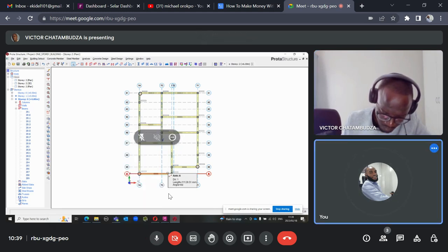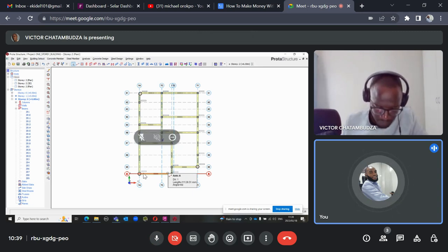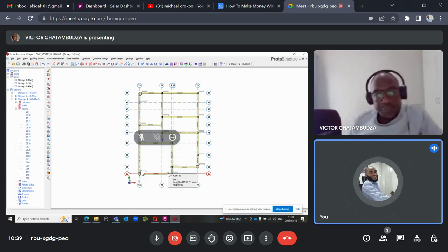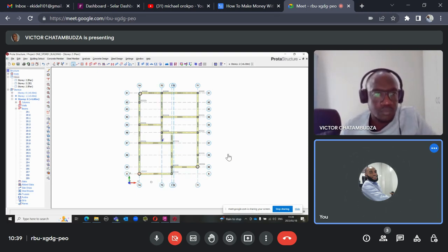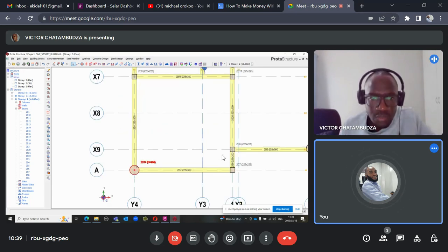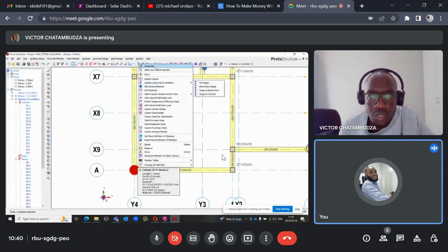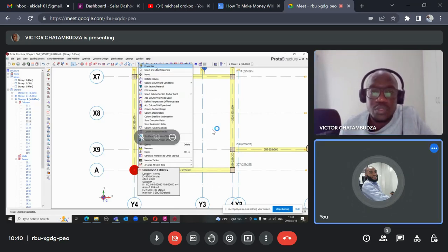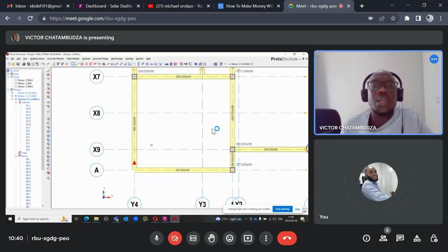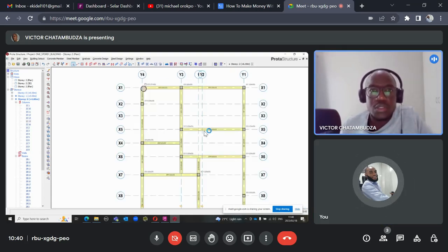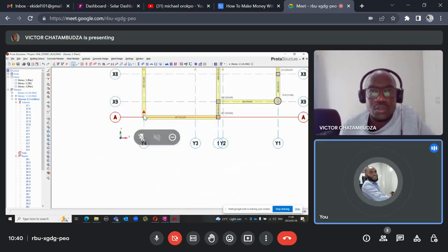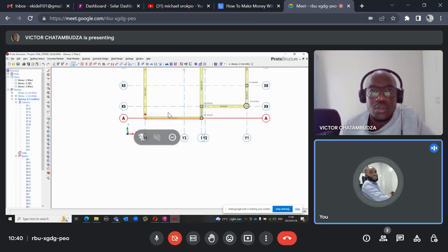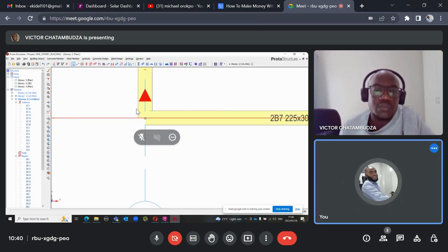Okay, sorry. Now, right now we want to remove the circular column first. Take off the circular columns here and then replace them with a square column. Take off the ones that are meant to be removed. Yes, that one should be removed, and then put a square column there. Do I just say delete? Yes, just delete. And then put a column there also. Yes, that one too. Just put a column there. You can take the column properties of the one that's already existing here. Click on one of the square columns, then see properties and then insert.